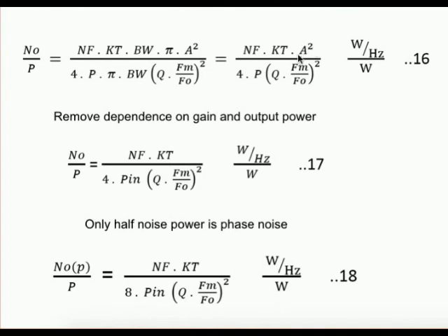We've got here A is the voltage gain of the amplifier, so this is the power gain of the amplifier, and this is the output power of the oscillator. Well, of course, in Robin's equation the output power of the oscillator was in there, but it was expressed in a different way, so this wasn't here. But in this more general equation we could express it like this, but it's better to express it in this form here, where we've replaced A squared and P by P in.